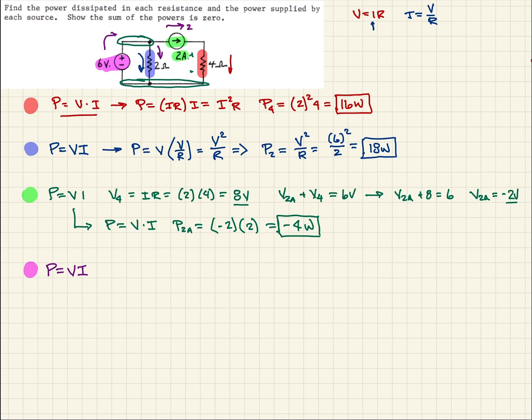So that being the case, we can invoke Ohm's law again. So in this case, we're looking for I. So I, we solved up in the corner there, is equal to V over R, right? So we know the voltage drop across our resistor. We've already said that's 6 volts because it's in parallel. And then the resistance is 2 ohms. That's given in the problem. So that would be 3 amps. So there's 3 amps going through our resistor.